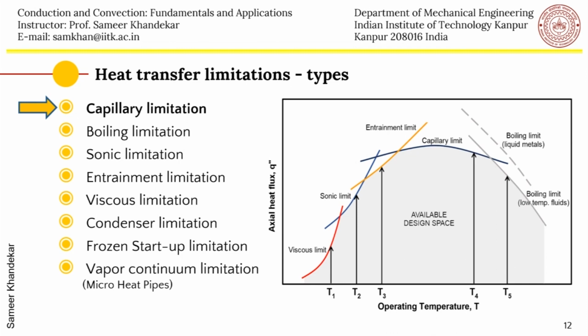Then your cooling atmosphere will be of the order of 50 degrees, so that automatically the evaporator temperature will not be very different from that. It will be slightly higher, depending on the thermal resistance. If you want to take the heat at 100 degrees centigrade, then naturally the outside ambient, with the circulating water or whatever ambient you are giving to the condenser, should be of that order of temperature, so that the evaporator temperature is accordingly adjusted depending on the thermal resistance of the device.